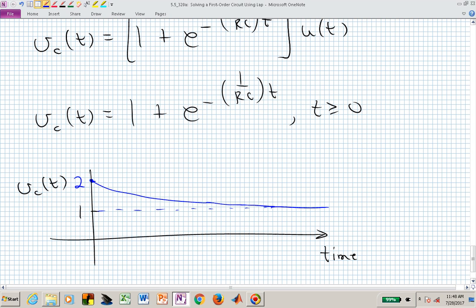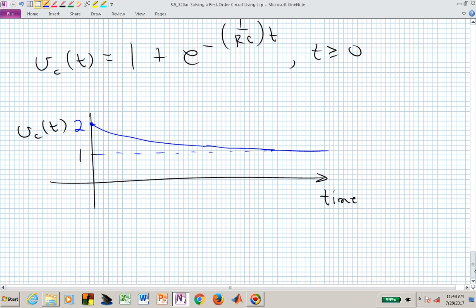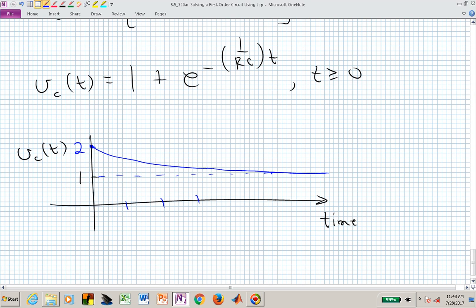And that's now what our time domain waveform will look like. Now, you might be saying, well, what's our time axis? Well, we can start to understand where we will be at what values from 2 to 1 by understanding this exponential. And the exponential is influenced by that value of s that solves s plus 1 over RC equal to 0, or it's influenced by this RC value.